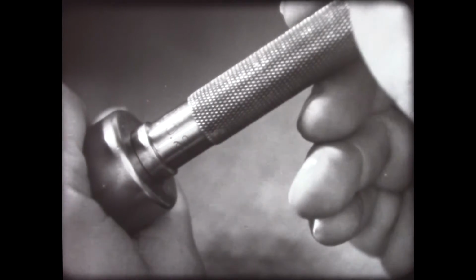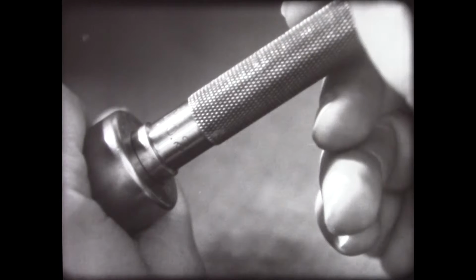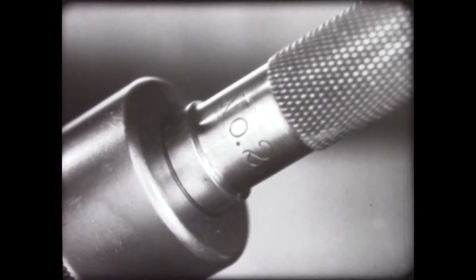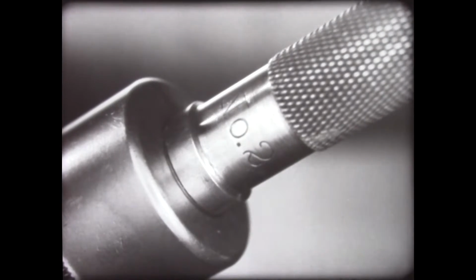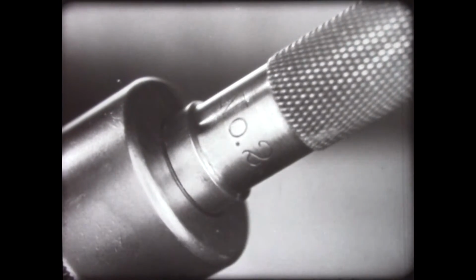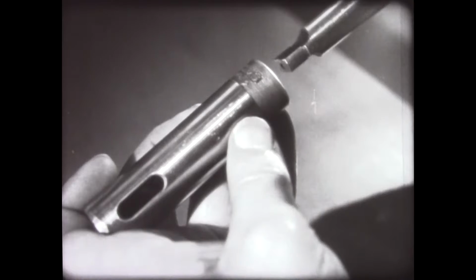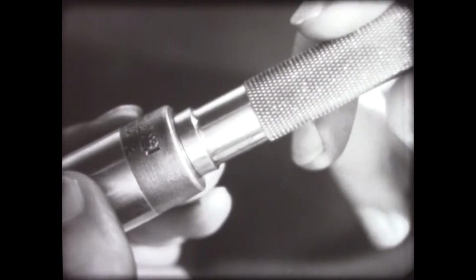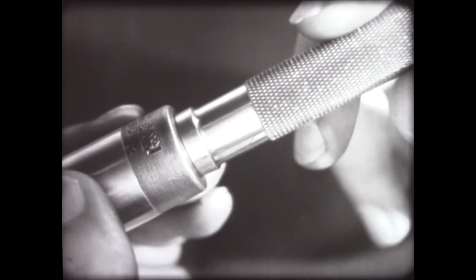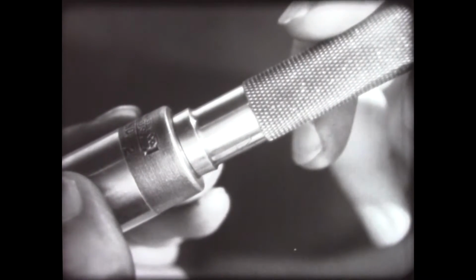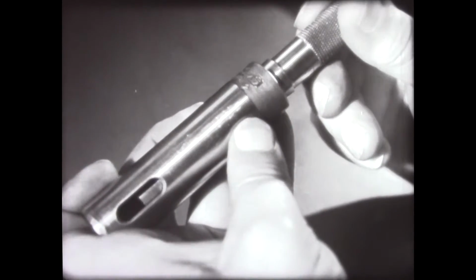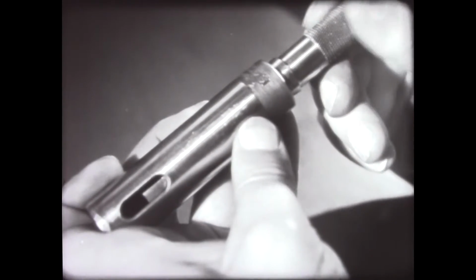If the taper is correct, the gauge cannot be shifted sideways, and if the hole is of the right diameter, the limit mark will line up with the end of the work. Another type of taper plug gauge has a tang at the small end. It is used to check the tang recess, if such exists in the part, as well as the taper and hole diameter. If the tang readily enters the recess and the taper fits the hole snugly, the part passes inspection.